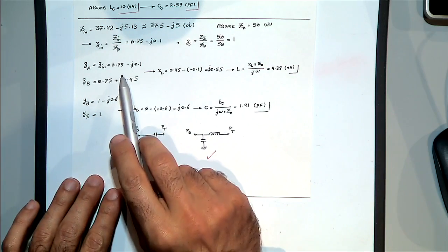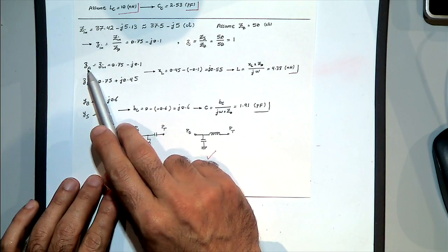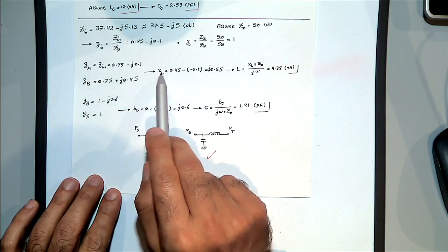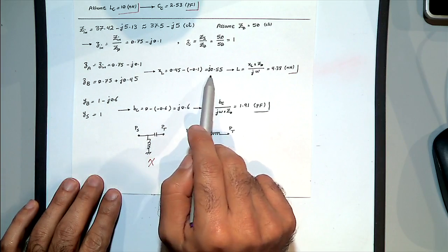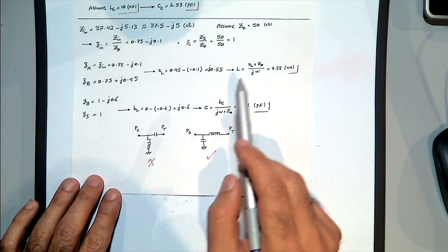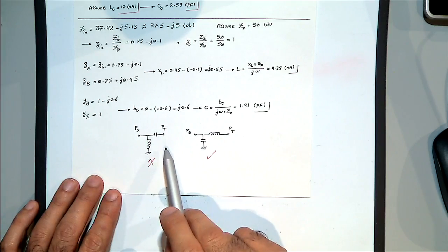And then based on the values that we got, I moved from point A to point B, and the XL I found is 0.55, and then at the frequency that we have, it is 438 nanohenry, and then the same thing for the capacitor.